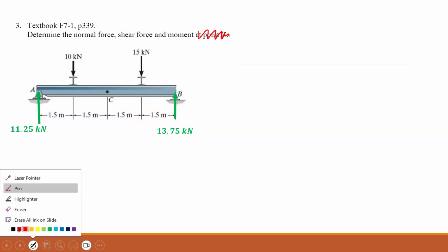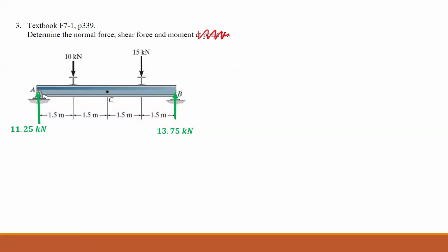Now we start from this left-hand corner and we go along the beam. When there is a load changing the loading system, we draw a line there. So again, I'm moving on and I can see loading conditions are changing. So I can divide the beam into 3 parts. So this is my section 1, section 2, and section 3. So what we did, we start from the left-hand corner and we walked along the beam. And when there is a change in the loading condition, we figure it out, like, we divided it into 3 categories depending on the loading condition.